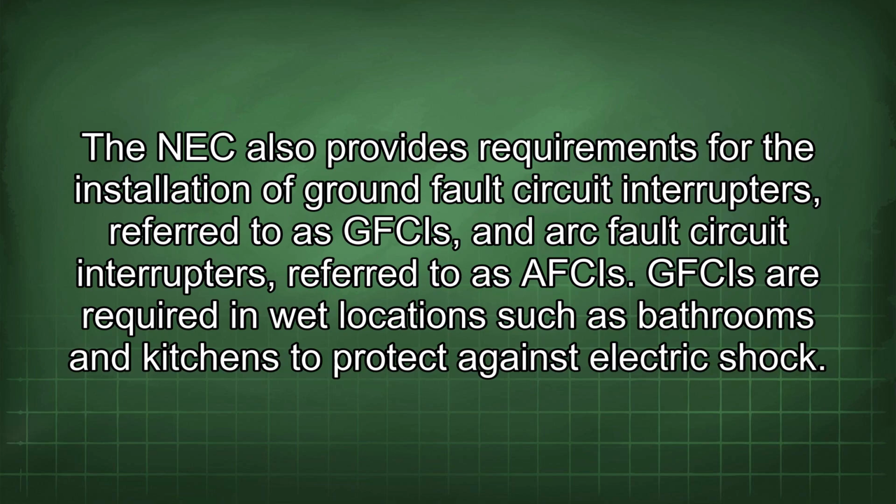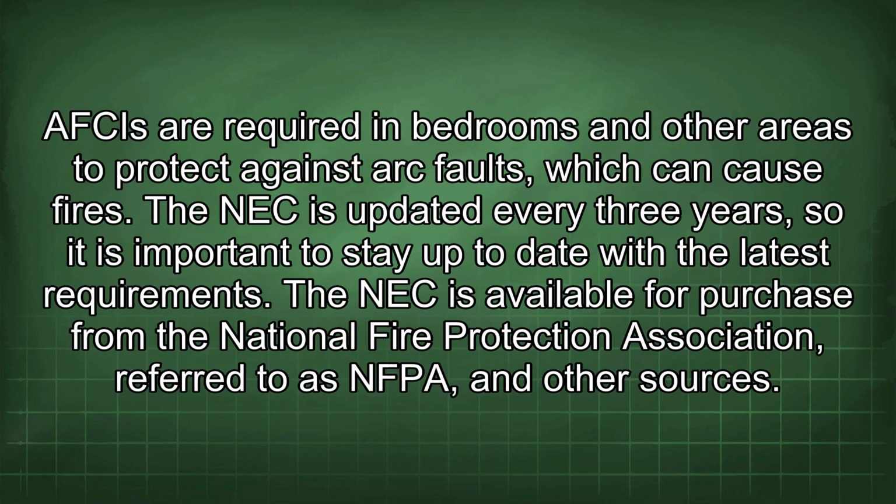The NEC also provides requirements for the installation of ground fault circuit interrupters, referred to as GFCIs, and arc fault circuit interrupters, referred to as AFCIs. GFCIs are required in wet locations such as bathrooms and kitchens to protect against electric shock. AFCIs are required in bedrooms and other areas to protect against arc faults, which can cause fires.